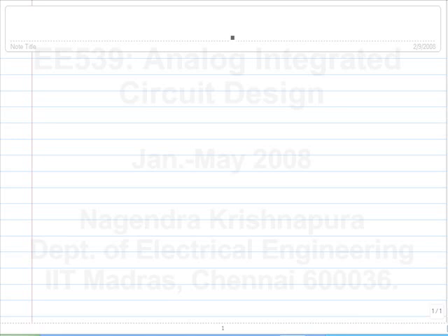Hello everyone. The last time we met, we were discussing the second assignment, in particular the design of the transimpedance amplifier. We looked at the transfer function of the transimpedance amplifier and we worked out certain trade-offs. The objective is to design the transimpedance amplifier with a certain gain RF, but because of the finite unity gain frequency of the amplifier, it turns out you cannot increase RF indefinitely.